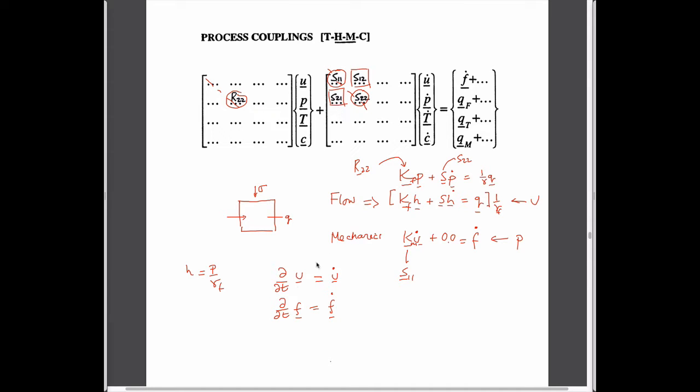So that's a good point. This means that if we take head and we multiply both sides by unit weight, then we get pressure. So actually we have to not divide it by this, but we have to multiply it by unit weight. So we multiply both sides by gamma, and then this becomes gamma, right? That's a good point, yes. So that gives us the right magnitude of this.